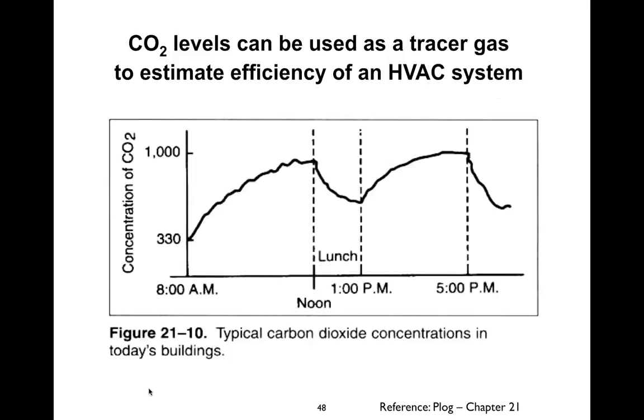So, as an indoor air quality person, I'd say to myself, I can't really say that they're not getting the required amount of outside air, that they're not getting the 20 CFM per person, because they're within 700 ppm of outdoor levels, which I'm presuming for a moment to be 350 or 400. But they're so close that it's really kind of marginal. You like to see a little bit of a cushion.